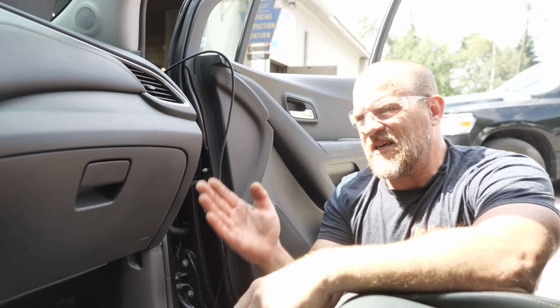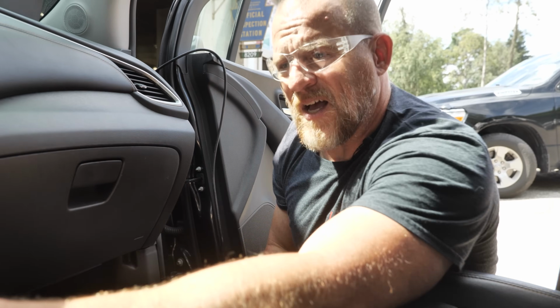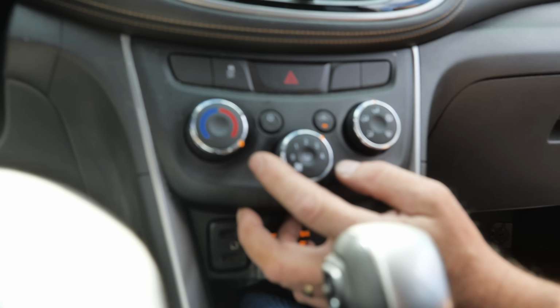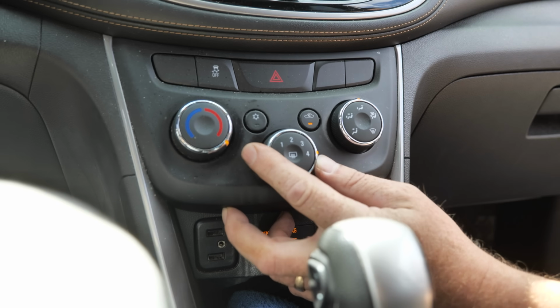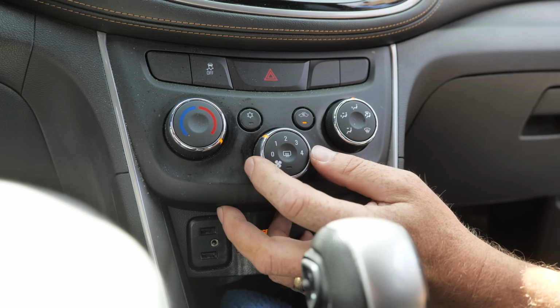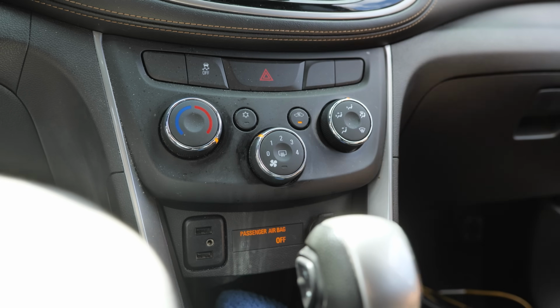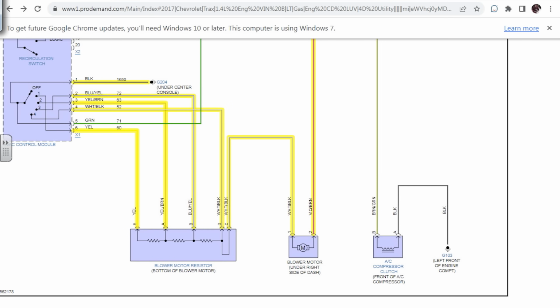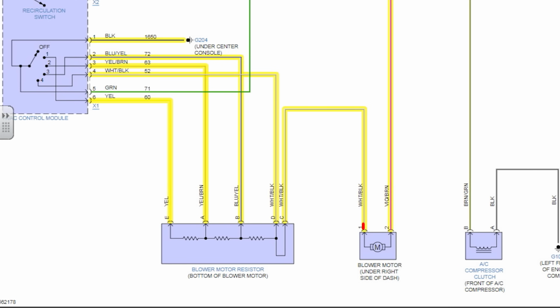The reason that we don't see corresponding voltage drops as I move this, because we should, as I move the switch, we should see high voltage on pin 1 because it's grounded. It's got to go through 3 resistors. So follow this in your diagram. This is my ground circuit. If I'm in position 1, it'll go through here, and it's going to try to go to 4. Can't go anywhere. The switch isn't connected. And then it'll try to go through 3. It can't go anywhere because the switch is not contacting 3. It's open in that section.